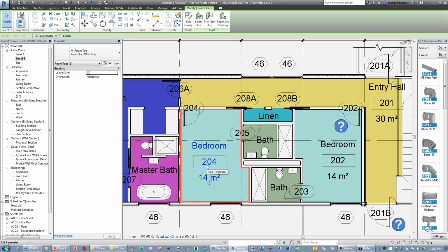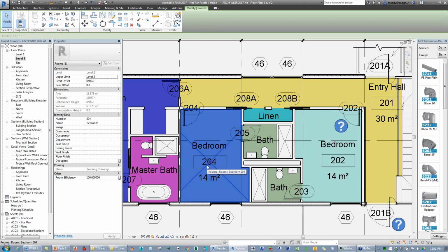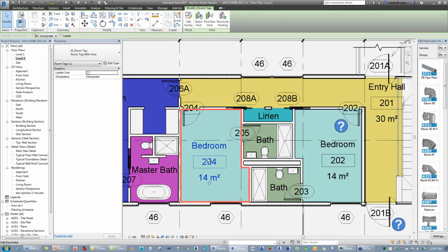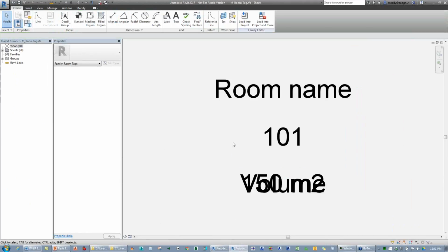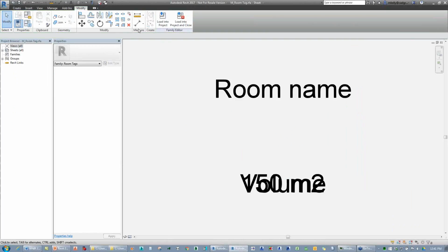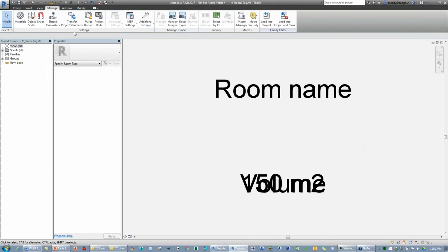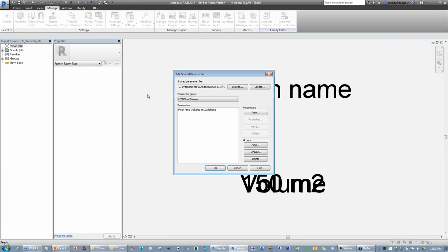And that's something that has existed in Revit pretty much always. You could always do shared parameters from the start. But I think the next part of it is this. If I click on that tag and delete that one, then what I've got to do manually is grab that shared parameter, because Revit doesn't see it here.